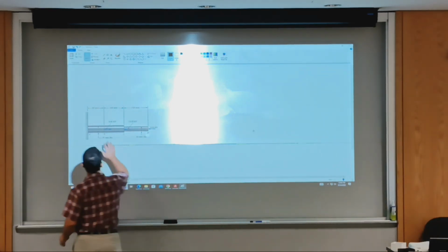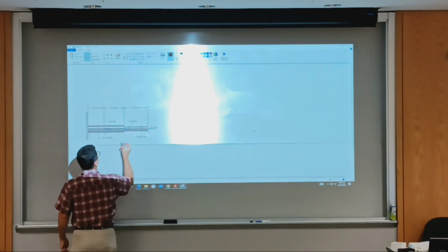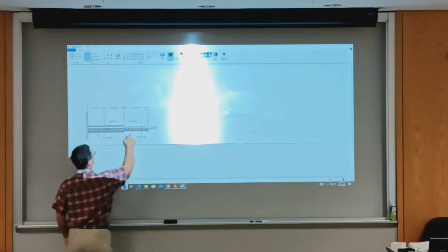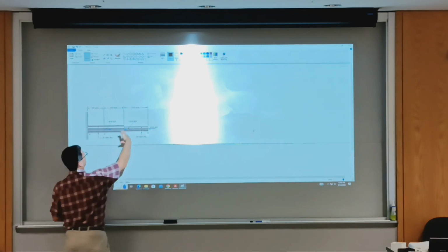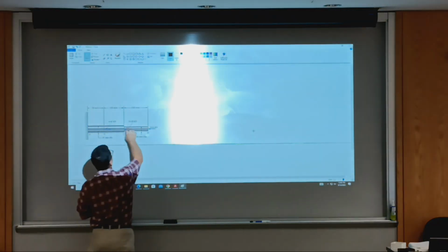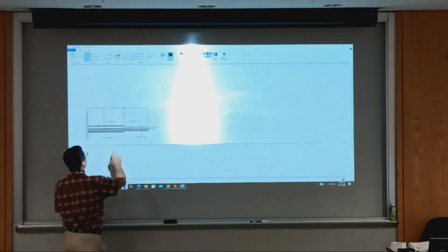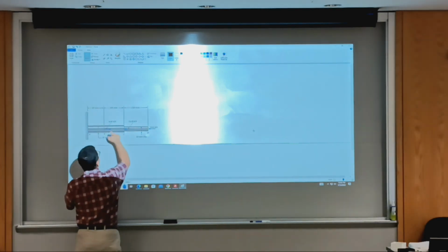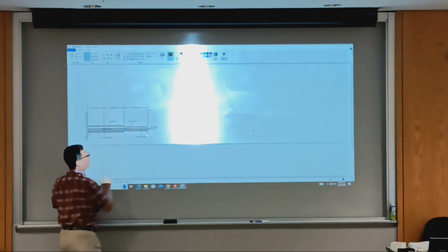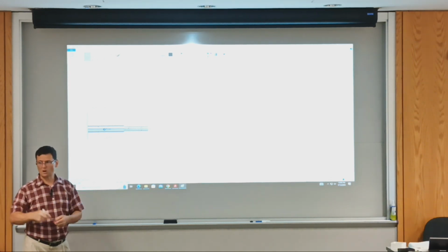So again, you have a stepped column, or could have been vertical. This load here, it might be clear how it's applied. So you have the step, and you can have a collar, and this 1232 kilonewtons force is applied through that collar. This other one, the tensile force, think of a hole there, and you have a through rod and you plug.